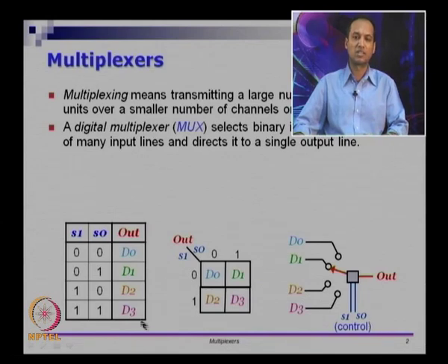So a multiplexer is not that, because you have only 4 combinations. Of the 4 combinations, multiplexer demands that one of the inputs is connected always, and outside the 4 combinations there is nothing else. So this is what is called a variable entered map. This is like a K map, only that we did not put D0, D1, D2, D3 as 4 different columns and wrote output based on that. Since we do not really care about what value D0 or D1 takes, we just put D0 here directly. So a way to do that in a K map is as follows. So when 0, 0 is, so this is the way I should interpret this K map.